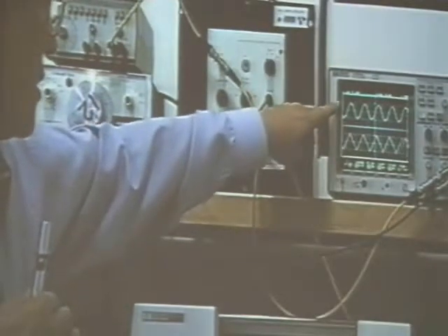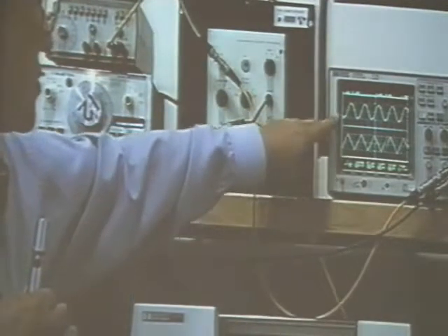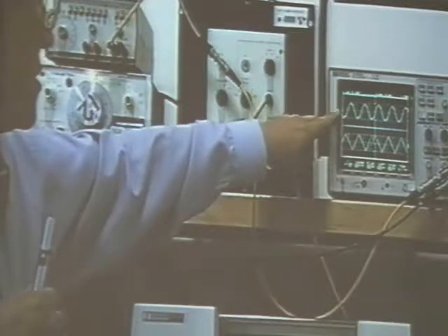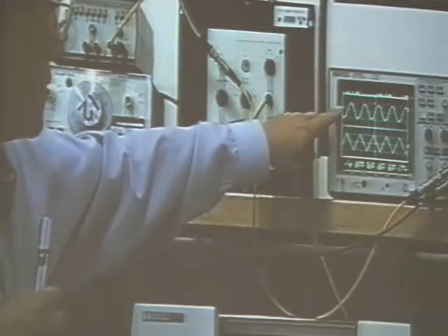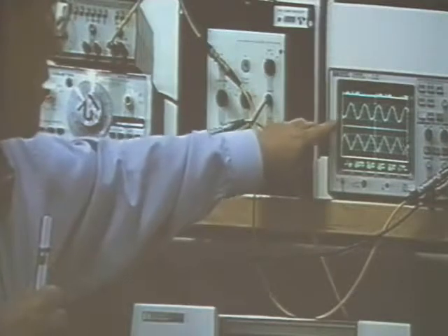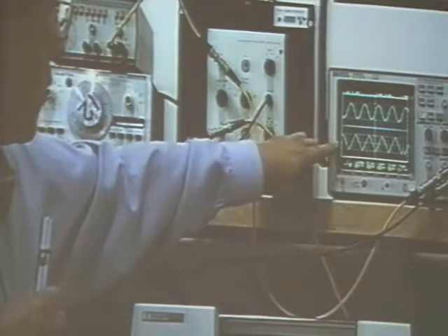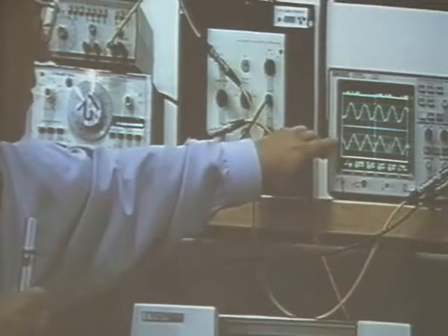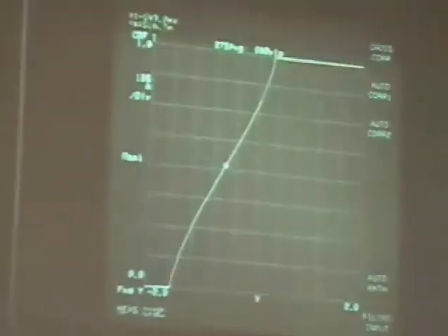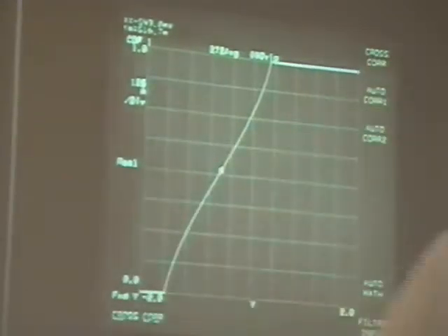So I'm going to show you the cross correlation of this to this, which means E, the mean of x(t) multiplied by y(t plus tau), for this triangular signature. So I'm going back to the digital signal analyzer. I set it to cross correlation, channels 1 and 2 are active, and the measurement is cross correlation. Then I'm going to start taking a measurement.